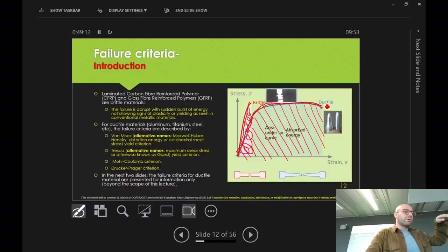So if the UAV or aircraft lands, you've got debris, or you've got lightning strike, or whatever impact you have on the structure, it can absorb that. Because for impact, you need energy absorption. So that Kevlar, which is often put at the outer mold surface, on the outer layers, absorbs that energy, protects the underlying CFRP, and allows that CFRP to act as a high stiffness light material.